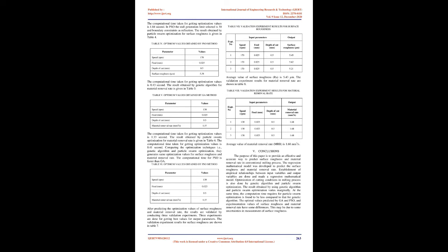In the fourth stage, genetic algorithm and particle swarm optimization are used to optimize the predicted models given above. GAs are algorithms based on the mechanics of natural selection and natural genetics, which are more robust and more likely to locate the global optimum. The cutting conditions are encoded as genes by binary encoding to apply GA in optimization of machining parameters. A set of genes is combined together to form chromosomes, used to perform the basic mechanisms in GA, such as crossover and mutation.